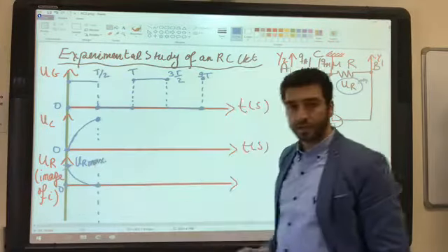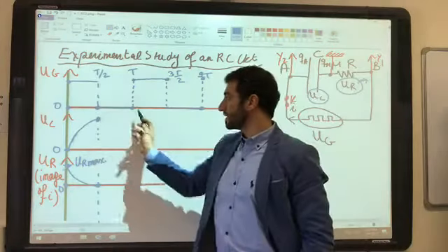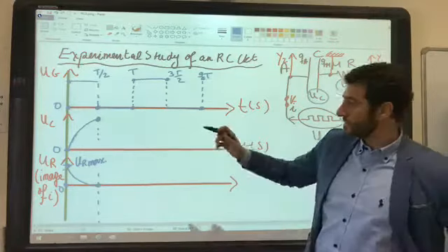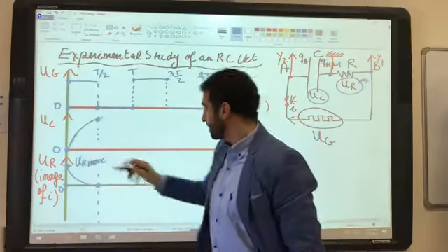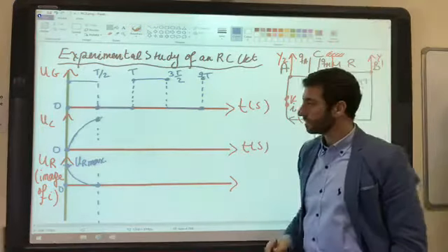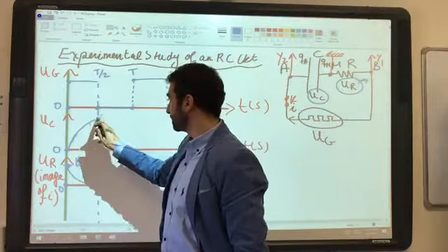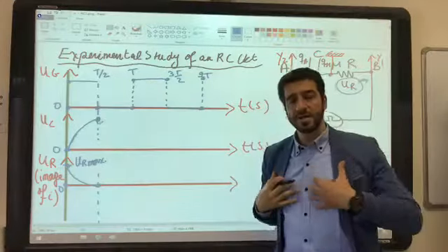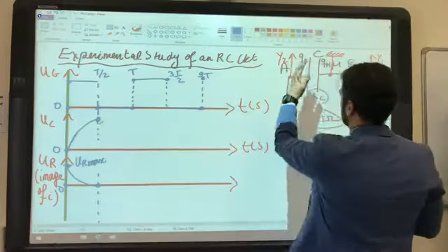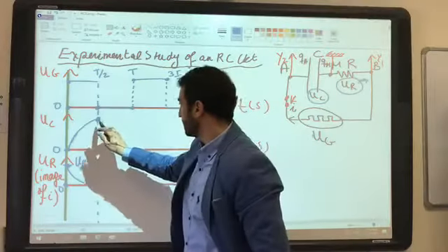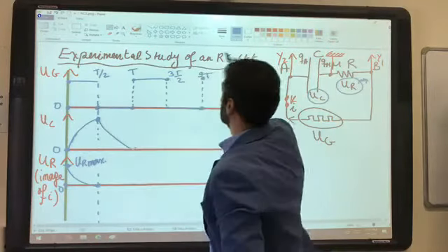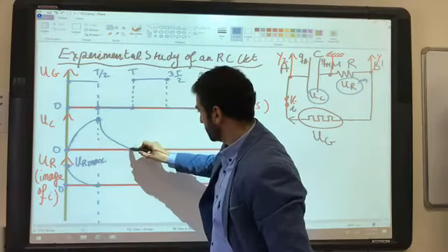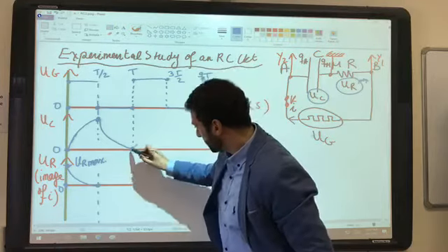And now the square signal goes to 0. When the square signal goes to 0, it is as if we opened the switch. The voltage is now 0, and the capacitor's voltage is now maximum. Whenever the capacitor has a maximum voltage, it tends to give out its voltage to the other side, so the capacitor will discharge going to one period.